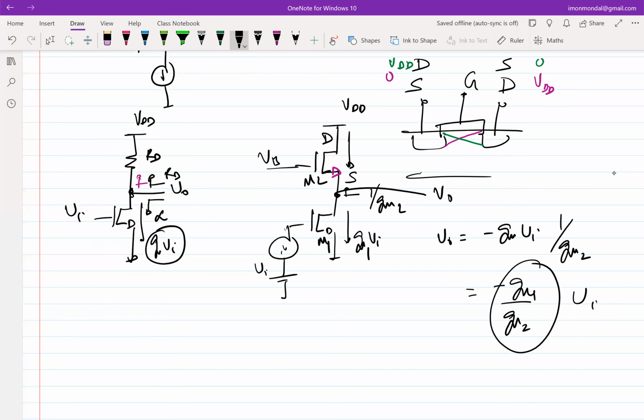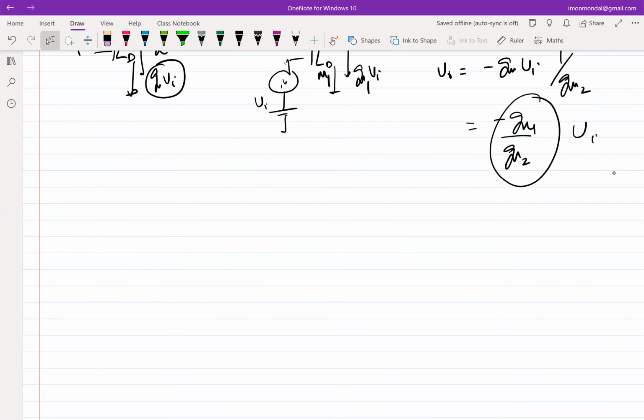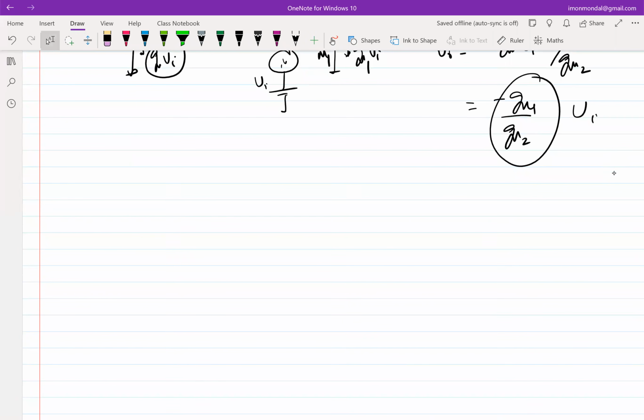Okay, the lower side of the terminal in a MOSFET is a source, and in order to fix this problem, you would want the lower voltage terminal to be the drain. Okay, so if we can get a device which behaves exactly like an NMOSFET, but just that the direction of source and drain are flipped, then the problem is solved. Okay, so as it turns out, there is a device, it's called PMOSFET, right? It's complementary to that of N. So let me sketch the device, you'll understand readily.